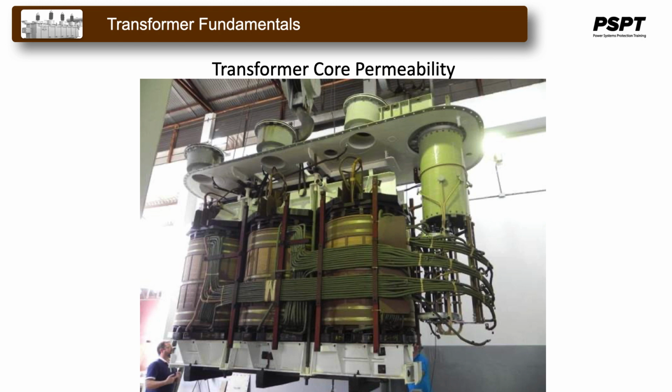This means that steel cores can carry a magnetic flux 1500 times better than that of air. However, when magnetic flux flows in a transformer steel core, two types of losses occur in that steel. One is termed eddy current losses, and the other is termed hysteresis losses.